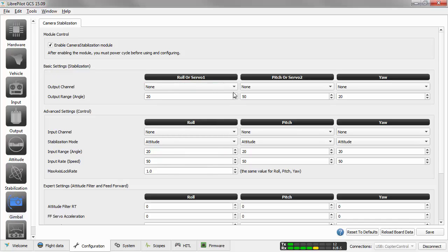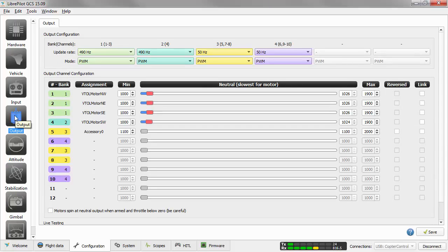If you're using a 3-axis gimbal setup, whether it's with servos or whether you're using actual brushless gimbal motors, then you can use the same type of configuration and allow the camera to tilt and pitch and yaw and do all these different things based on the attitude of the entire device, the quadcopter. Again, we're not getting into that. We want manual control, so we're using these inputs and output values so that we can manually tilt the camera up and down. So at this point, notice that we have a green check mark next to save.